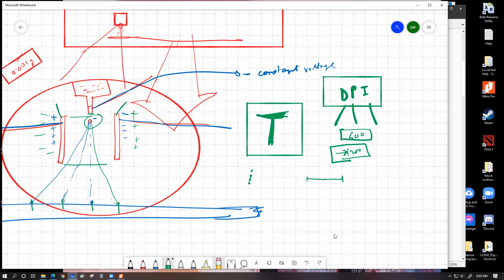Yeah, that can also be done, and I totally agree with your point. In many printers, that is also an adopted design. We can keep one of the plates always connected to a ground connection, which will always be 0 volt, and the other plate will be controlled by positive or negative. The benefit of having both of the plates able to charge in opposite charges is that you can achieve a much stronger field.